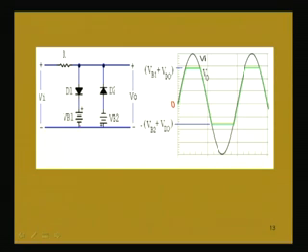So, V naught will be equal to Vi for this portion. Now, whenever Vi is greater than VB1 plus VD naught, the diode D1 conducts and the voltage will be equal to VB1 plus VD naught, that is why it will be constant. Then again, when Vi is less than this voltage, the diode D1 will not conduct and input voltage and output voltage are the same. It will be continuing in the negative half cycle.